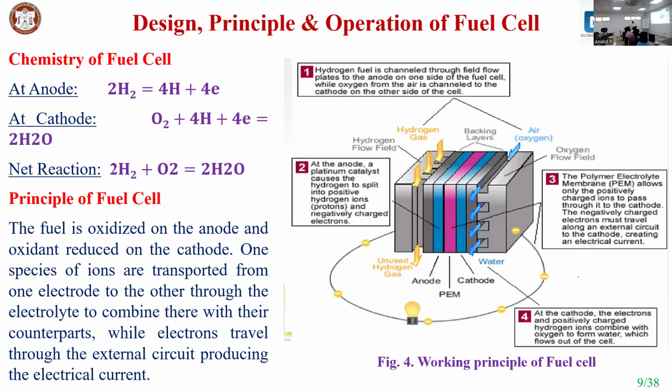So, anode, cathode, electrolyte, then fuel entry, oxidizer entry, and then collecting the electrons that come from the anode to the cathode. That arrangement is also necessary. Whatever is unreacted, the unoxidized hydrogen, is recycled back into the flow channel. Similarly, if the oxygen does not break down into O minus, it can be sent again into the input of the oxidizer unit.